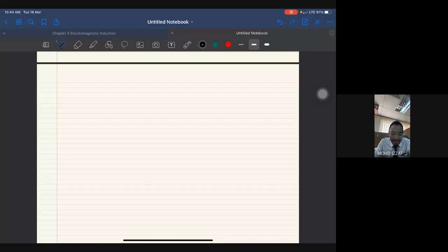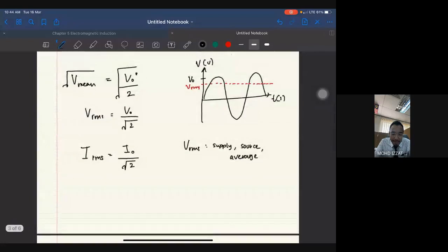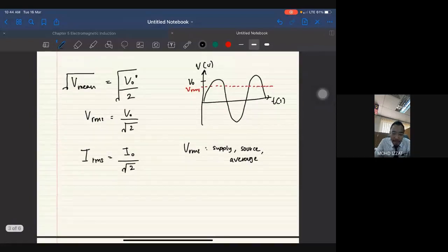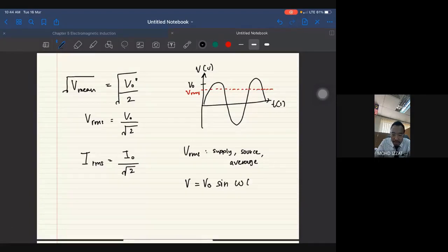The next part is actually if you want to discuss. Okay, sebelum saya skip, saya nak tekankan something. This graph actually saya boleh represent with an equation. V equals to V naught, this time dia adalah sin, omega t. Kenapa sin? Because the shape is sin. It depends on the shape lah. Kalau ada cos, dia jadi cos. Omega is actually equals to 2 pi f. Frekuensi dia. Kalau frekuensi dia 50 Hz, masuklah 50 Hz dalam tu. Sometimes kamu boleh pakai juga sebagai 2 pi over T. Jarang-jarang lah, but maybe you can use.